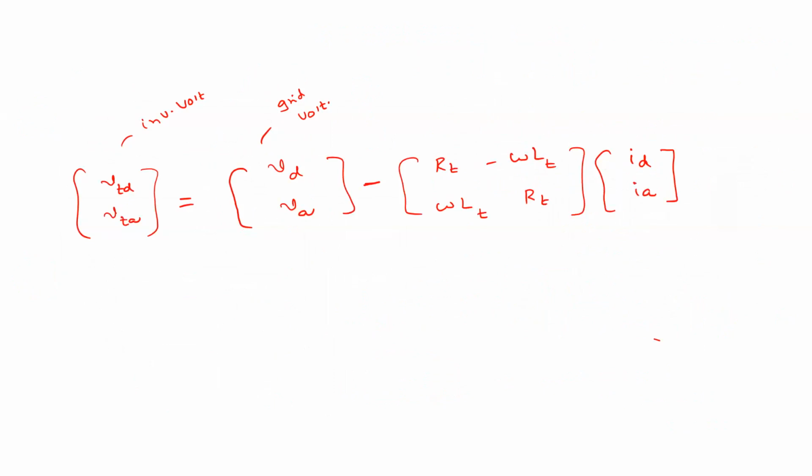Okay. So in addition to that, our objective is to control the D-axis and Q-axis current, right? So you require a PI controller to process the error. That will be ID star minus ID. Similarly, IQ star minus IQ.